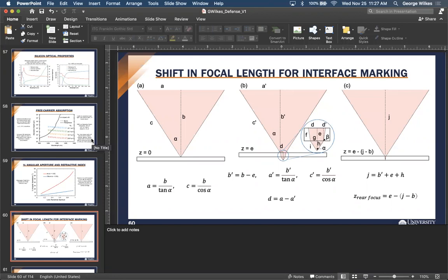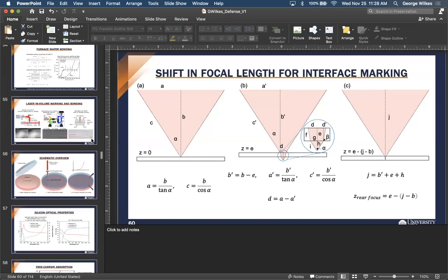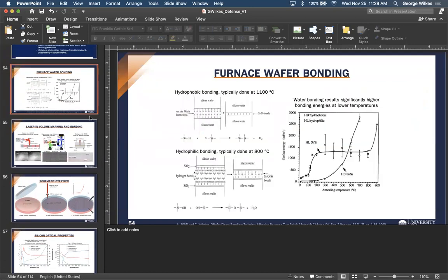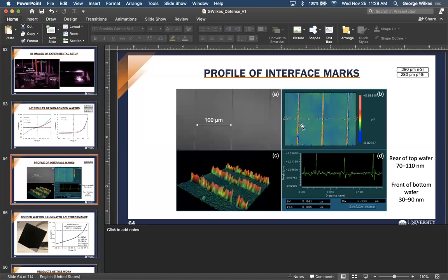So do you think it will melt the interface to make a diffusion-based bonding, or does it just activate the surface energy to bond together the oxide interface? What is the working mechanism? I don't think in your case, yeah. In my case, I definitely had melting, and that assisted with the bonding. But obviously, the melting temperature for silicon is 1400 Celsius, so you don't need anywhere near that to get the bonding with these other methods. I see. Yeah, you can get the bonds without melting. But for this project, obviously, I'm inducing these lines of melt that are roughly 100 nanometers high.